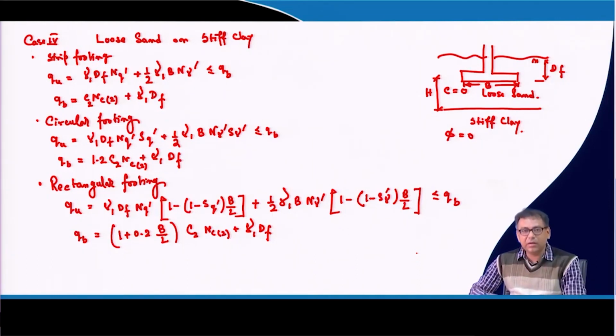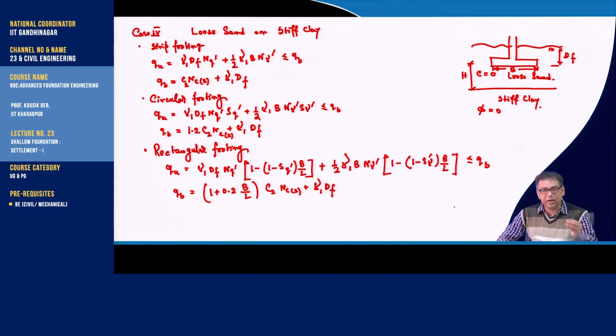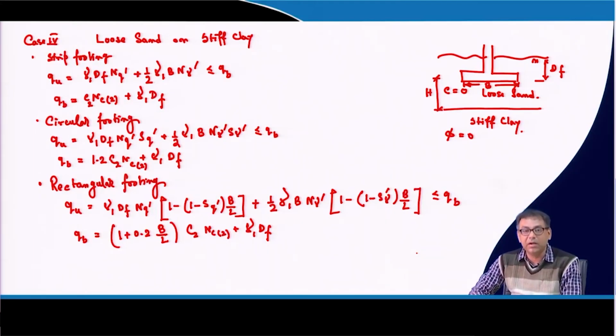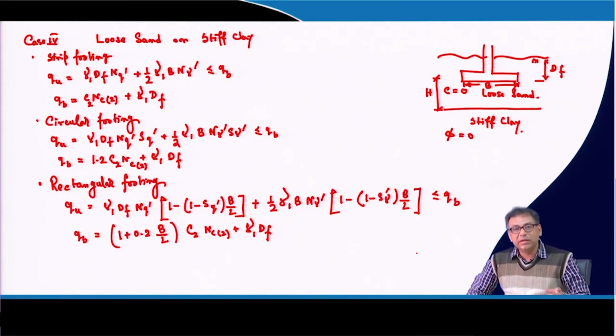That is one way. Another way, some researchers have suggested that when the soil is weak, instead of taking full C, you take 2/3 of the C value, which is recommended by Terzaghi for local shear failure, the 2/3 of C and tan inverse of 2/3 of tan phi. So you do that also, if you are sure that this soil is very poor, weaker soil, that means there is a possibility of local shear failure, or basically just to reduce the bearing capacity.